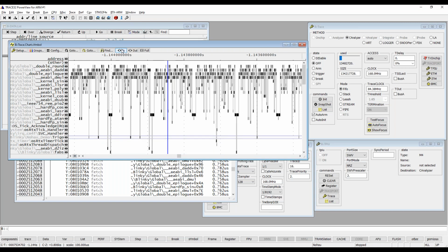But notice that you are only sampling once every 128 clock cycle in this case. So there are functions that you will not catch in this chart here when you do it with the PC sampler. I will come later on another alternative with it that is a lot better.